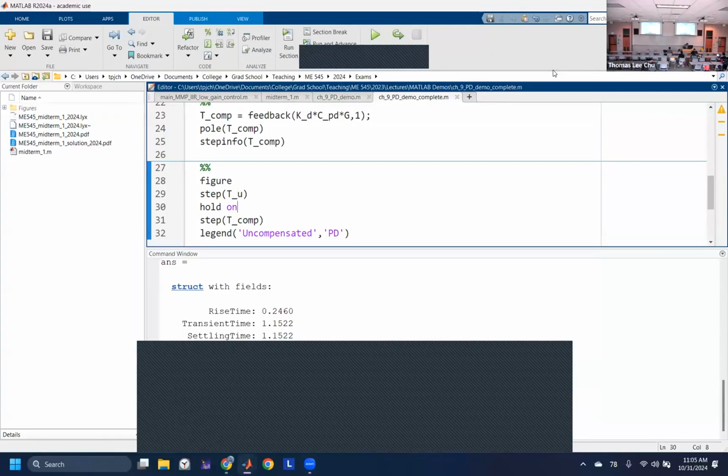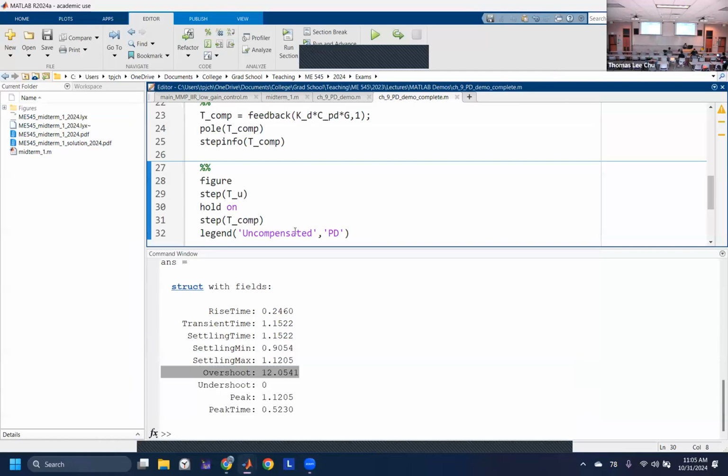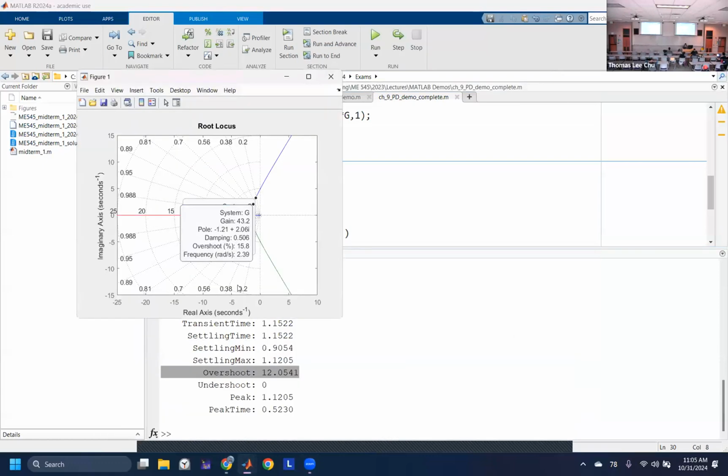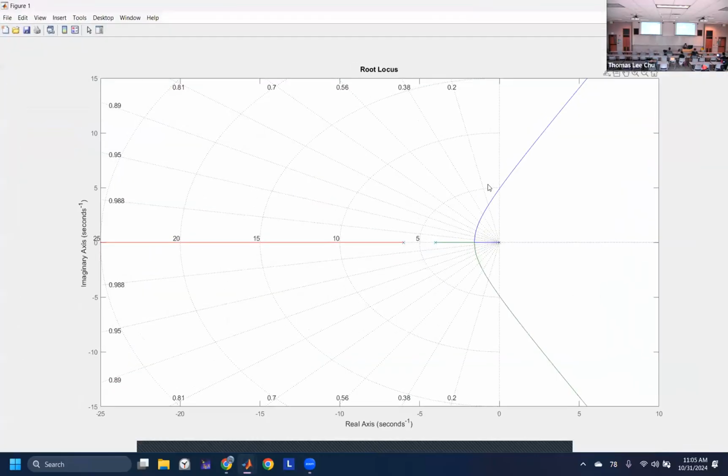there's actually one other thing I want to show you on MATLAB, so sorry to jump back, but also to answer your question. When we go back to that root locus, because we're using the root locus of our original system, it's still the system here. One thing I do want to show you, I forgot to mention it, so that's why I'm coming back here. You see these little diagonal points? Those are your zeta lines.